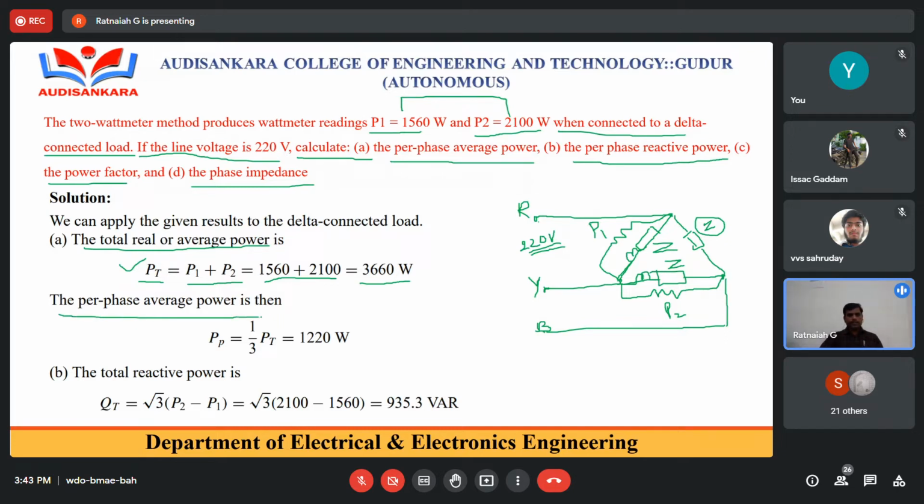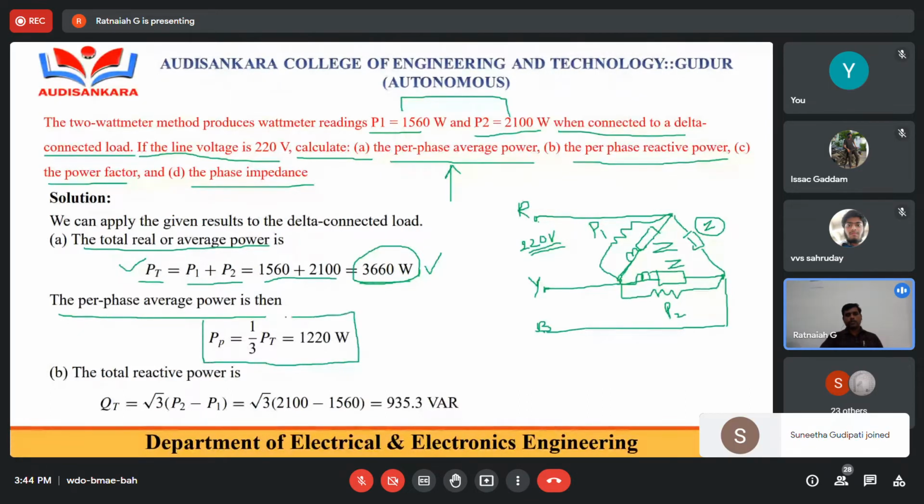Then what is the per phase power? Because he is asking about per phase power. What is the total power consumption? 3660 watts or 3.66 kilowatts. Per phase power we require. So how many phases are there? It is a three-phase system. Obviously, there are three phases. Now the total power is 3.66 kW. Then what is the per phase power? That is nothing but total power divided by 3. Therefore, the per phase power is always equal to the power absorbed by the load divided by 3, that means one third of PT.